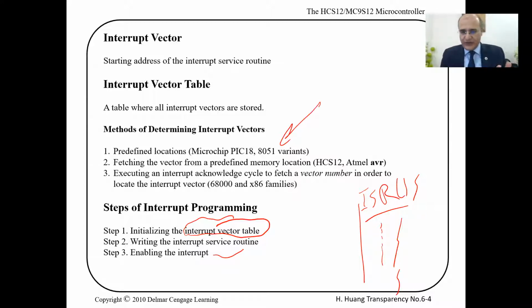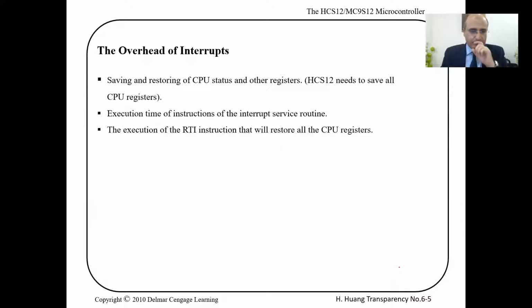This is for the first interrupt, the hardware interrupt. Later on, with another type of interrupts, and only if we exclude the hardware IRQ interrupt, at the interrupt service routine, you need to clear an interrupt flag, something called an interrupt flag, so you don't come back again to the interrupt service routine. I'll talk about that later.